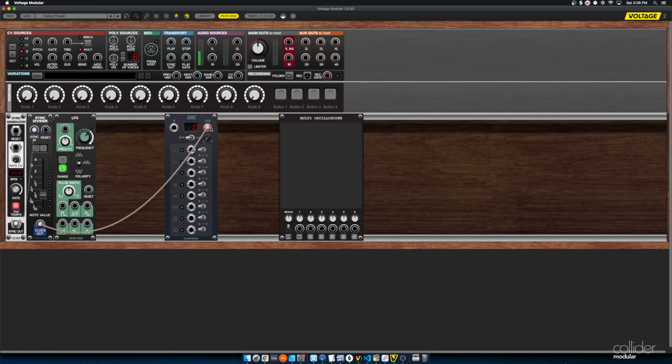There's a second thing that we need connected to Zadc in order to make this work, and that is some kind of incoming control voltage value. So I have an LFO going over here, and I'm just going to patch that in, put the sine wave in. Now you notice that as soon as we do that, a handful of things start happening. First of all, this number up here at the top is changing. And second of all, these LEDs down here are turning on and off.